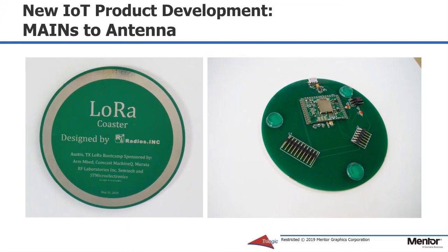So here it is in the flesh. This is actually what the board looks like. These aren't really the best photographs, but on the one side, we have nothing but copper. And on the opposite side, we have a breakout board with a radio and a very simple interconnect, one for programming, one for a terminal program, an FTDI interface, a simple jumper, and power with a little bit of ESD protection on a USB interface. But really, the radio and sensor is on a breakout board here.